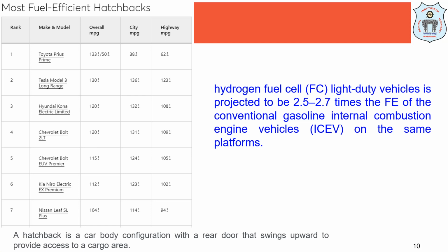That is, it is ranging from 2.5 to 2.7 times. Okay. So the key to obtaining this high fuel economy, measured as the standardized urban and highway drive schedules, lies in maintaining high efficiency of this fuel cell system at low loads also. To achieve this, besides a high performance fuel cell stack, we have to reduce the parasitic losses in the air management system.